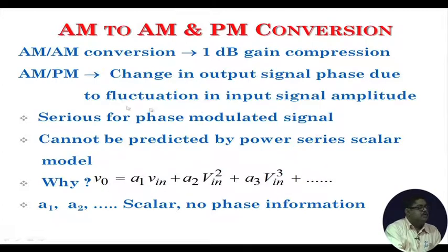But you remember that there is a phase modulation when we have nonlinearity, because when your input signal is fluctuating, Vin is changing, you are squaring it, cubing it. So, that is changing the phase of the output signal.